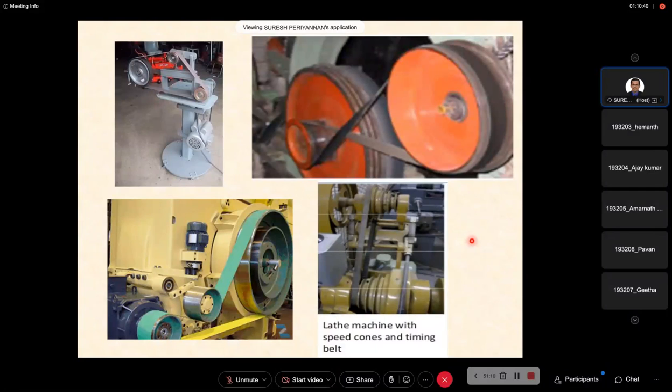But in a belt drive mechanism, especially a flexible drive mechanism, the driving wheel and driven wheel, or driving pulley and driven pulley, you may say that some books mention the pulleys rotate in the opposite direction when the belt is connected simply as an open belt. I mean, when the belt is simply connected on the driving pulley and driven pulley, both will rotate in the same direction.